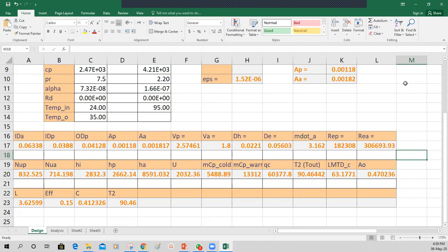Another thing that we need to check is at what temperature you took the properties of water. If you took the properties of water at 90 degrees Celsius or so, then you don't need to repeat it. But if you took 60 or 80 degrees Celsius, then probably you need to repeat it, because if there is a 10-15 degrees Celsius temperature difference, then the properties will change. Then the length will come out to be different. You got my point? Yes.